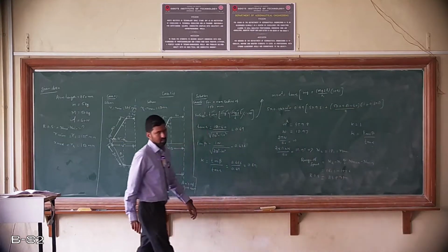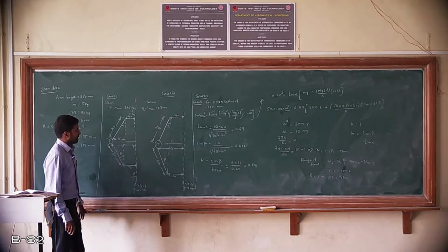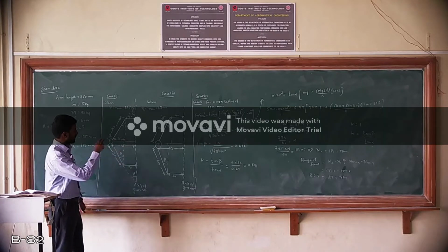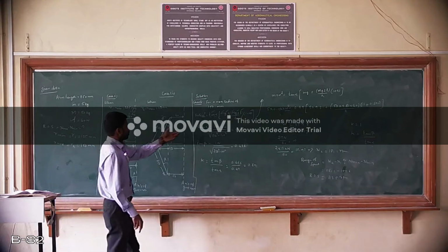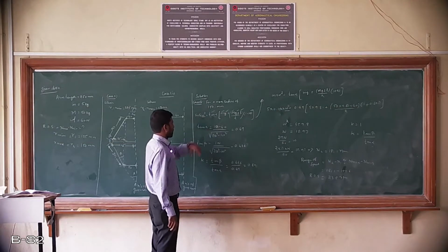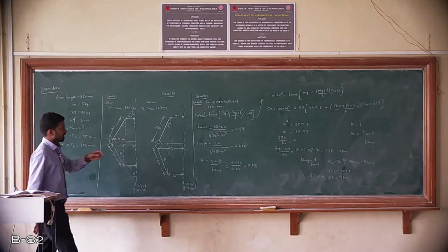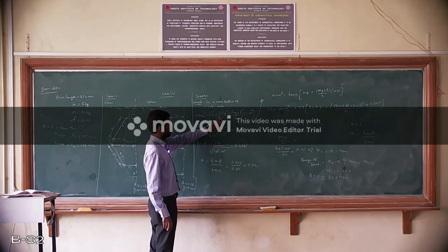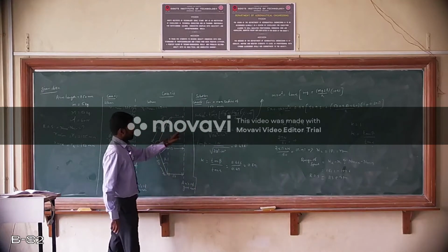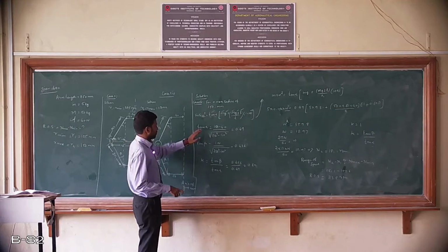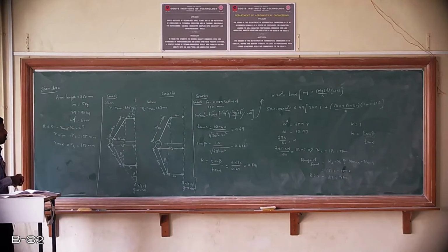And today we have discussed the third problem where the upper arm as well as the lower arm, both the arms, are not at all connected to the axis. So once again, to get the value of k, use the equation tan beta by tan alpha, and you will arrive at the solution. You can use this equation also, that is mr omega square is equal to tan alpha, or you can use the other equation which we have used for problem number 1, that is omega square is equal to 1 by mh into bracket mg plus or minus f into bracket 1 plus k whole term divided by 2. In that case, once again you need to calculate the value for h using the equation of tan alpha. So this completes all the varieties and all the problems on Porter governor.